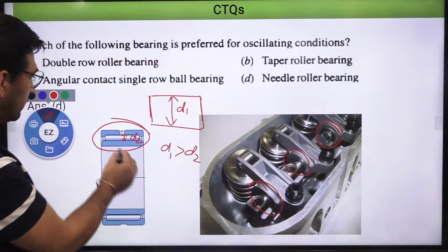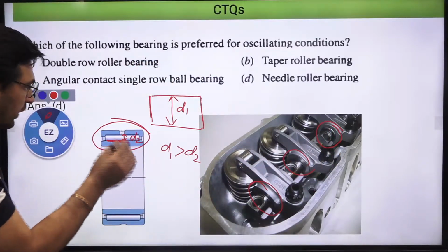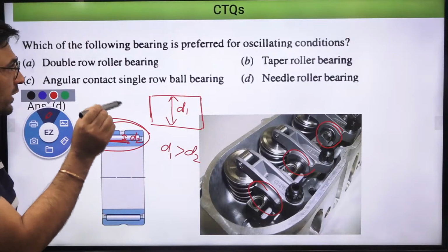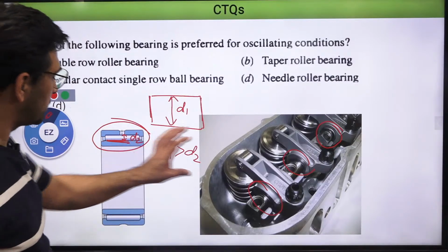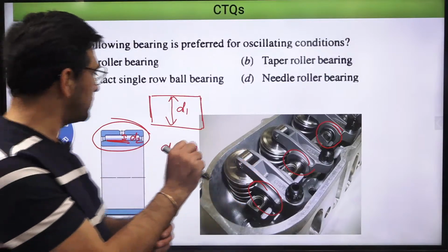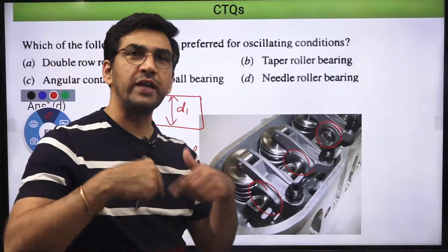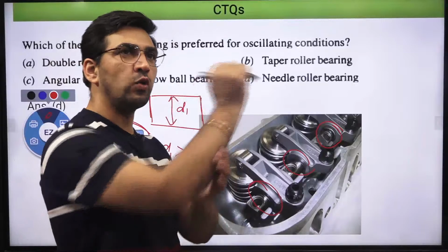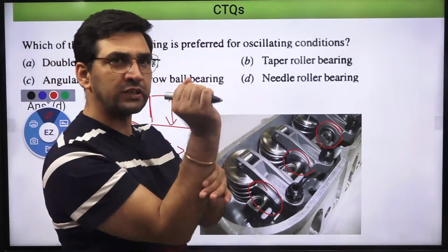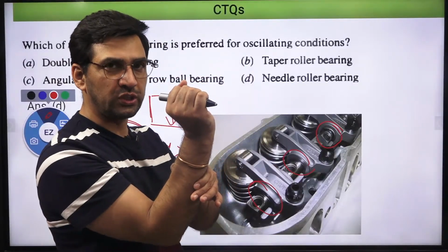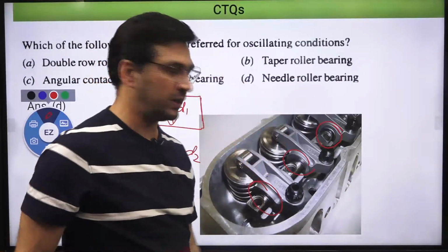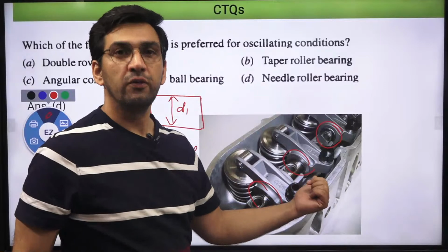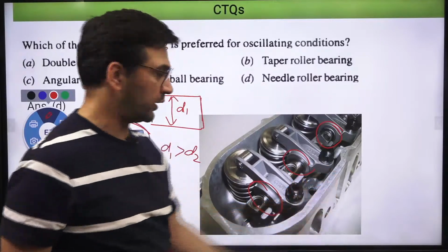So we are having rollers, needle rollers. The name is given as needle rollers. Why? Because their diameter is very small, like needles. So space saving also takes place. At the same time, because we don't provide cages over there, in one rotation they go forward, and when it reverses, they come back to their own position. So they don't gather at one location in this kind of motion, and therefore friction cannot be that much over there, right?